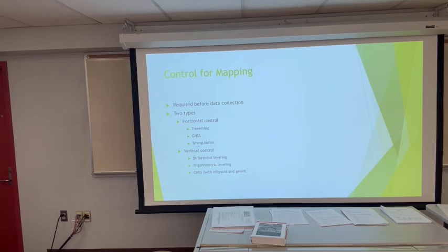You move to the other end of that baseline, backsight that other end, turn an angle to that same point you referenced from the other one. You have the interior angles, it's a triangle, you can start calculating distances around. Then you'd move to another station, backsight that initial baseline point, and then that new one, turn out. Just kind of keep turning triangles and calculating as you go.